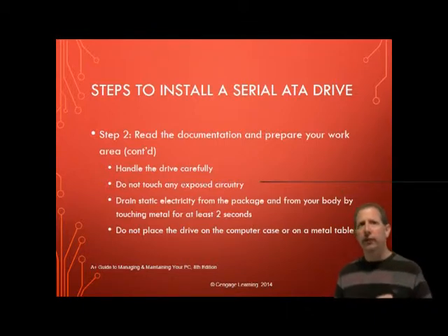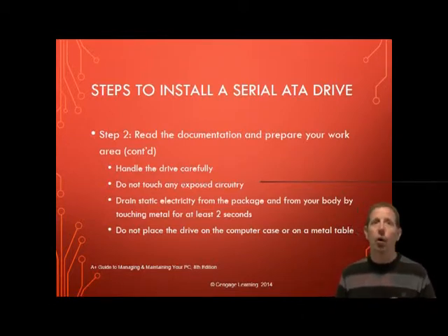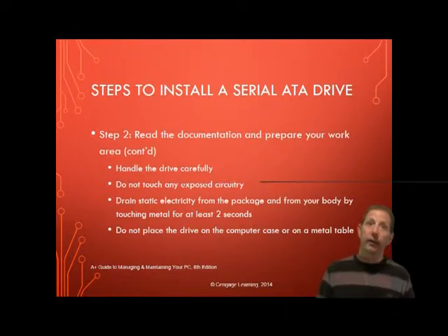And when you first take the drive out of the static protective bag, touch the package containing the drive to a screw holding an expansion card or a cover, or to a metal part of the computer case for at least 2 seconds. This will drain any static electricity from the package and from your body. And if you must set down the drive outside the static protective package, place it component side up on a flat surface. Do not place a drive on the computer case cover or a metal table. And if you're assembling a new system, it's best to install drives before you install the motherboard so that you will not accidentally bump sensitive motherboard components with the drives.